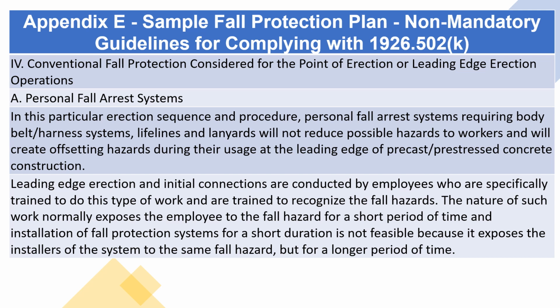Leading-edge erection and initial connections are conducted by employees who are specifically trained to do this type of work and are trained to recognize the fall hazards. The nature of such work normally exposes the employee to the fall hazard for a short period of time, and installation of fall protection systems for a short duration is not feasible because it exposes the installers of the system to the same fall hazard, but for a longer period of time.